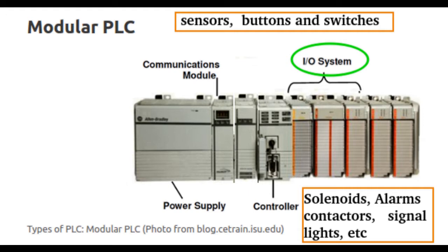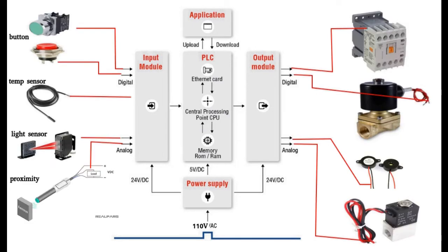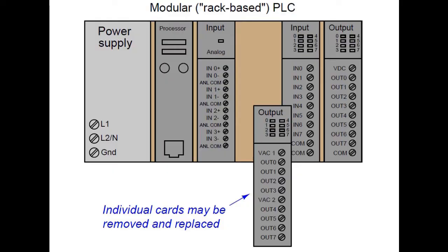the output modules. Typically, several times per second, the PLC will ask the input module the status of its connected inputs. Then the PLC evaluates and makes a decision based on its program and will determine what needs to be energized or de-energized via its output module. You cannot connect outputs to an input module or vice versa. Input or output modules can be either analog or digital modules.